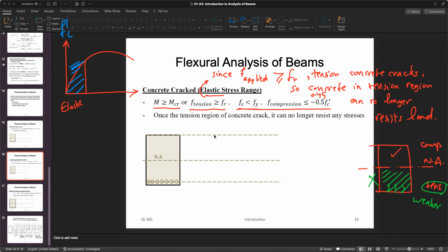That's what we discussed, right? So let's look at the strain, and this one is stress. For the strain, the deformation, you know that you have the concrete strain maximum on top. It goes to 0 at the neutral axis. It continues in the other direction, like in tension, let's say. So it would be epsilon of the steel.